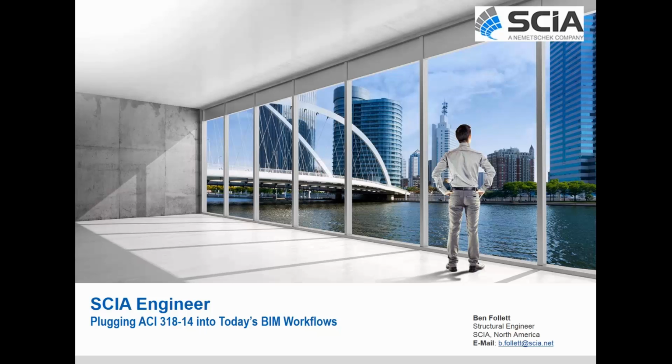What do you mean by cracking? So like, yeah, sure. In the ACI, I think I could probably handle the question. There are some provisions for the cracked moment of inertia for beams and columns and stuff like that. Yes, of course, and not only that, you shouldn't design a building with uncracked properties.